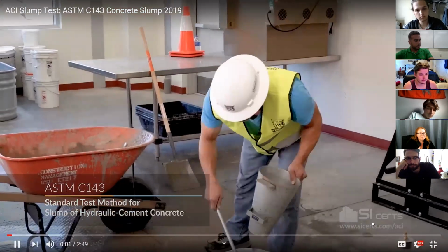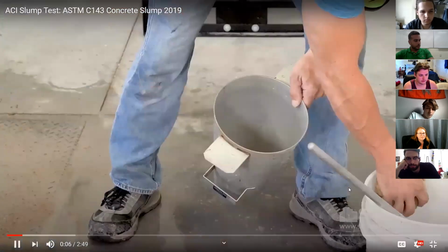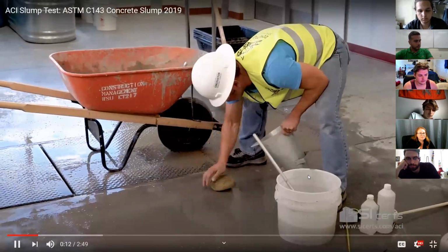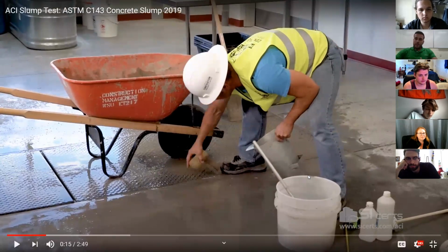Make sure that your slump cone is moist both inside and out. You want to perform this test on a flat, smooth, rigid surface, free of any vibration.